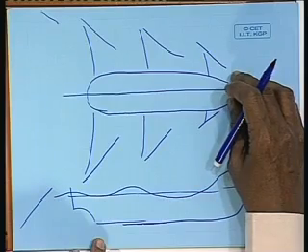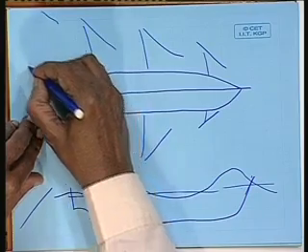Now, for the time being, if I just mention to you that the pressure point represents existence of high pressure, that is being generated as we have seen at the forepart and at the aft part. We have seen the pressure distribution around the ship in the initial class. There will be two peaks at forward and aft, and there will be a loss of pressure in the middle. Okay. So, that high pressure point in the forward end will give rise to a wave system like this. Similarly, the high pressure point in the aft will give rise to another set of waves.